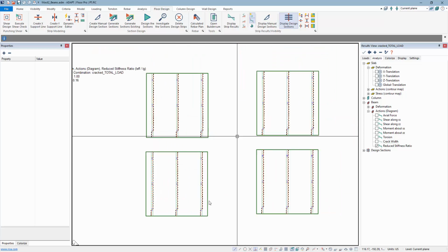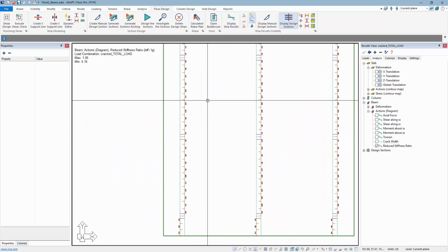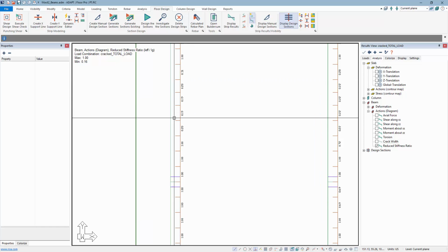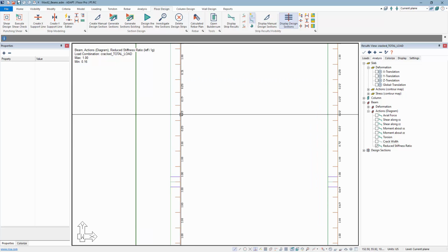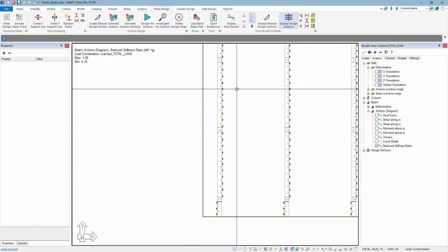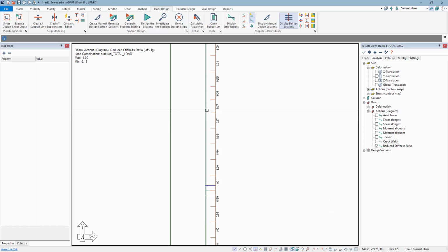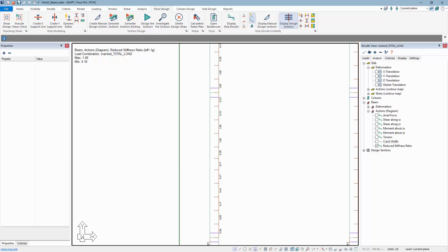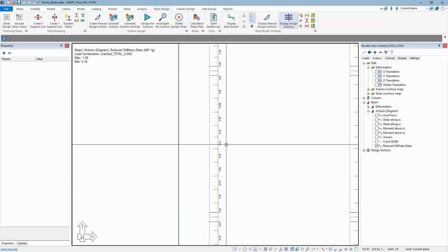On the RC side, we have something similar. We have 0.31, 0.2, 0.19. So this is lower. Obviously, we don't have the counteractive nature of the post-tensioning cables in those beams, so we have more stress on the bottom fiber at midspan, to 0.17, and then we get 0.16, and then the lower value here is 0.16.